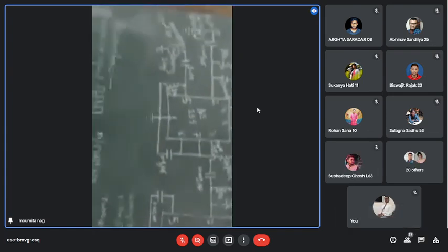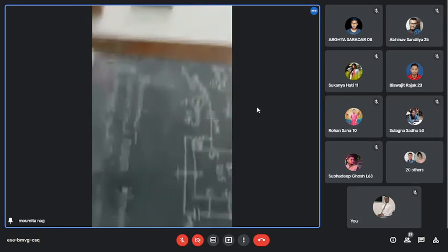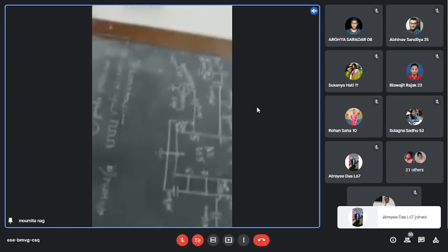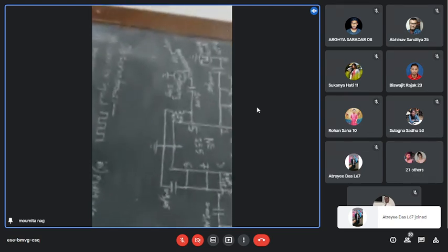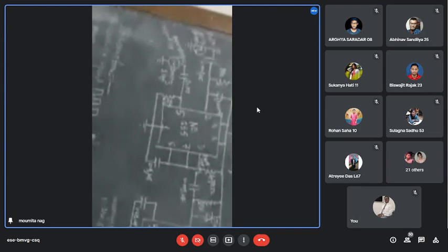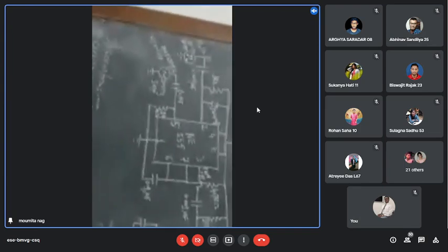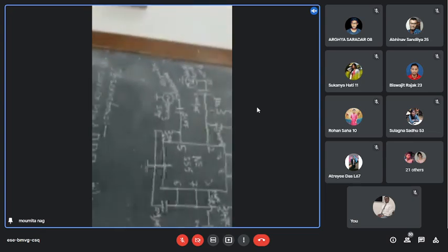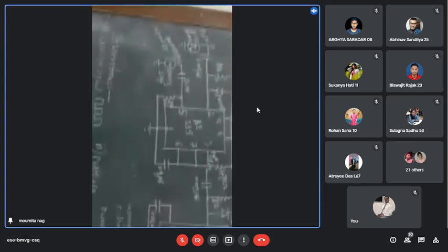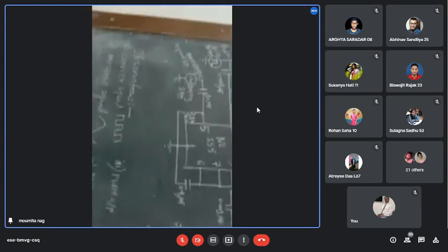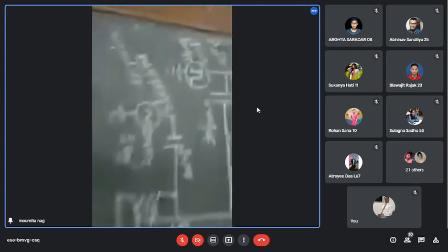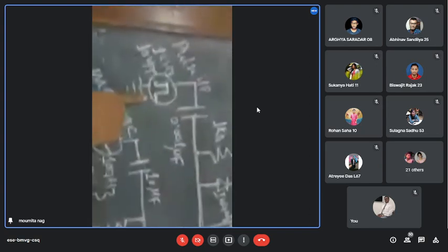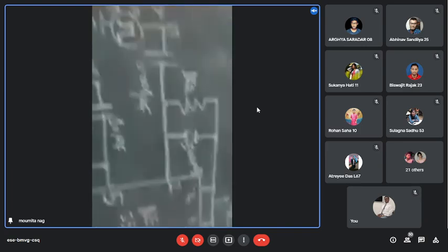In the last PWM circuit, the timer was working in astable mode, so one square wave pulse was self-generated for that circuit. But in today's circuit, one pulse is given at pin number 2, that is the trigger. See here, one pulse is given at pin number 2.